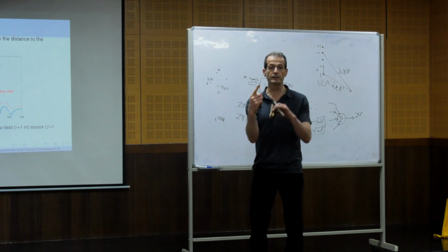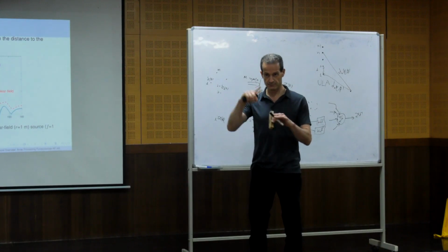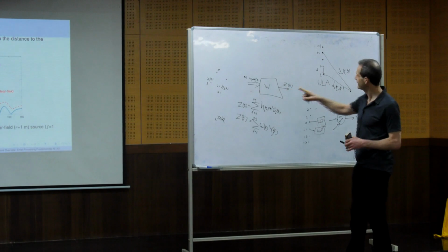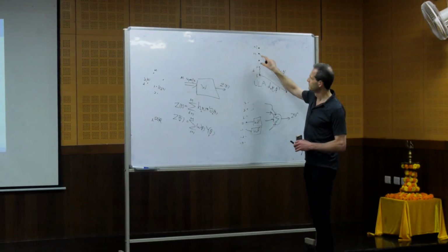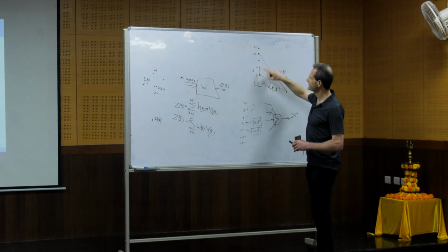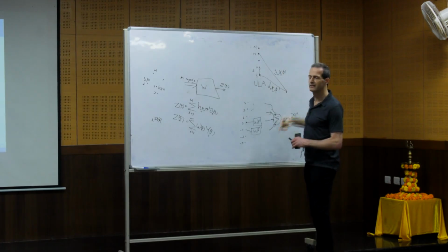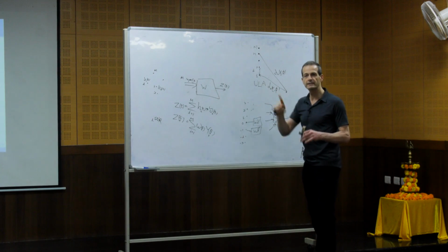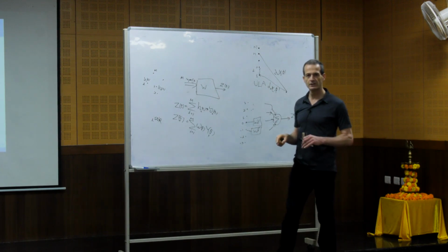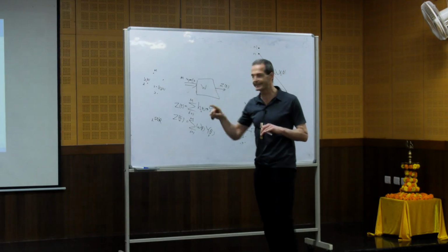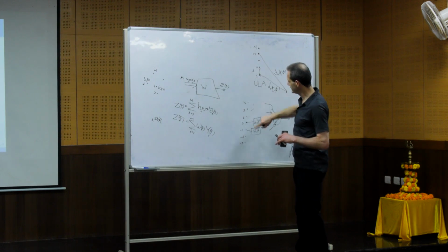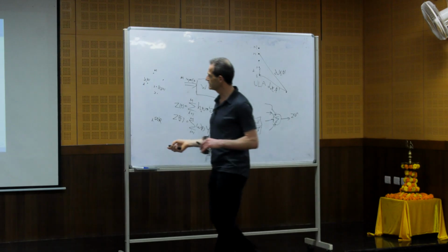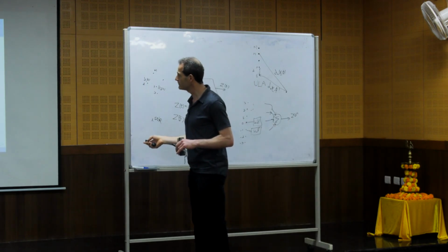Yes, it's spherical. So the differences are in the phase. Okay? So in the phase. It doesn't go like something horizontal. So the differences in phase between two sensors are different than in the far field. But also the decay, the magnitude. So these two factors, especially the decay, because the decay depends on the distance, make this near field directivity beam pattern such that it doesn't cancel.